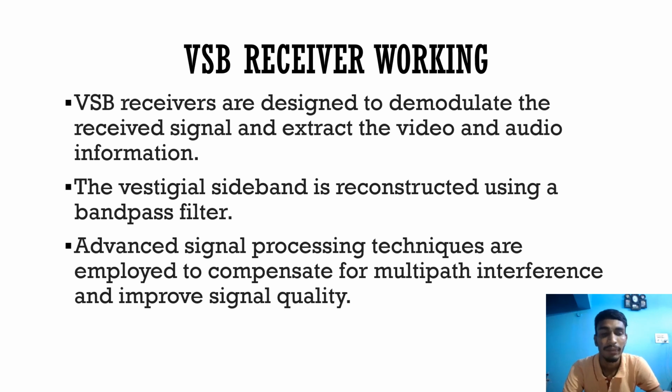VSB receiver working. The VSB receivers are designed to demodulate the received signal and extract the audio and video information. The vestigial sideband is reconstructed using a band pass filter. Advanced signal processing techniques are employed to compensate for multipath interference and improve the signal quality.